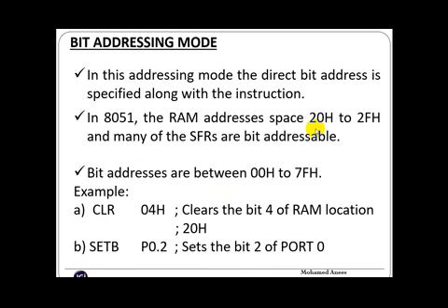The bit addressable area is 16 bytes. It starts from 20H to 2FH. Okay, and the bit addresses are between 00H to 7FH. So for this you have to refer to the internal RAM organization of 8051, which has been explained in detail.